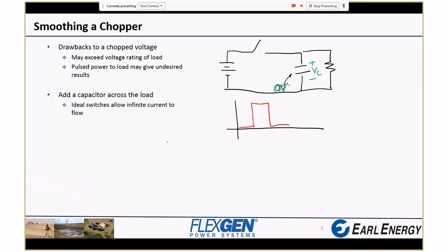Now the capacitor voltage comes along, and you don't want it to jump all the way up there. But the circuit you've created with this perfect switch is that you connected the battery in parallel with the capacitor. And like we said in earlier sessions, devices connected in parallel get the same voltage. Nothing you can do about it.